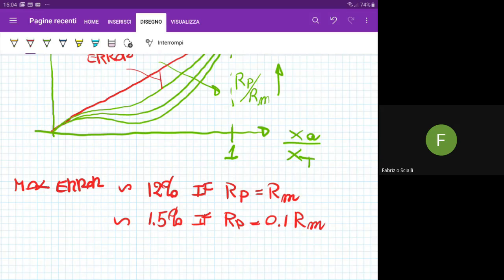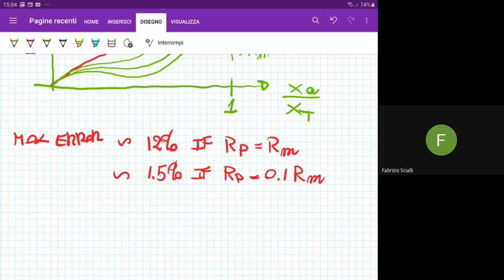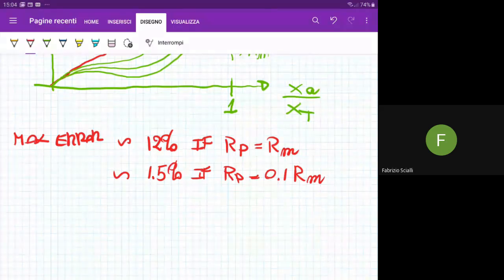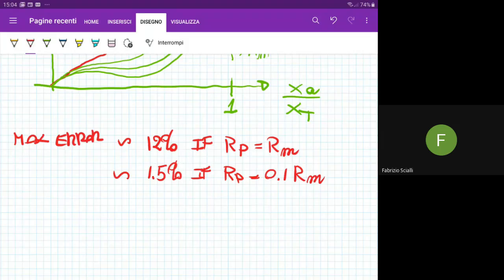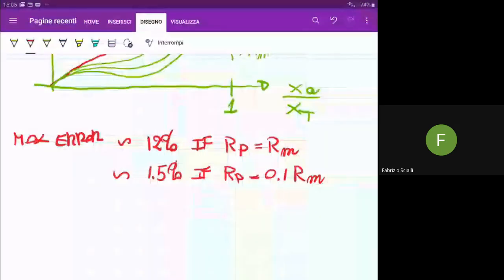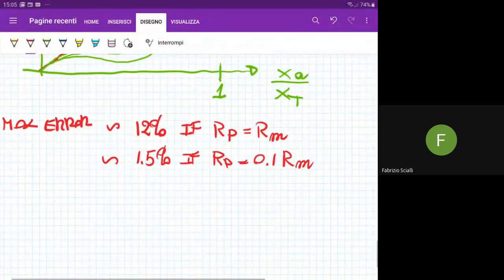As a general way of operating this kind of transducer, you have to use the largest measuring circuit resistance possible. This is why you have to check datasheets and then ask your service to provide you a different potentiometer or a different measuring circuit, so that the measuring circuit resistance is much larger than the potentiometer one.